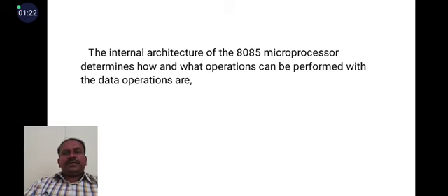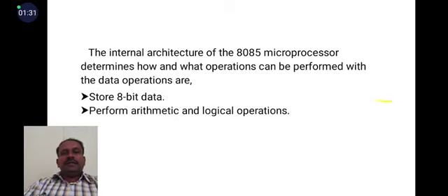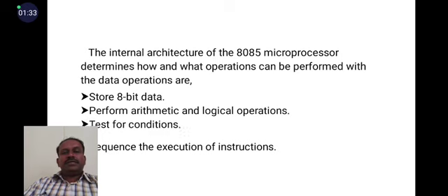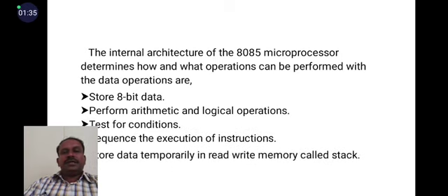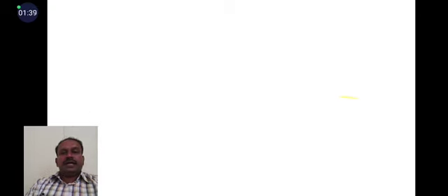The internal architecture of the 8085 determines what operations can be performed with the data: store the 8-bit data, perform arithmetic and logical operations, test for conditions, sequence the execution of instructions, and store data temporarily in read-write memory called the stack.